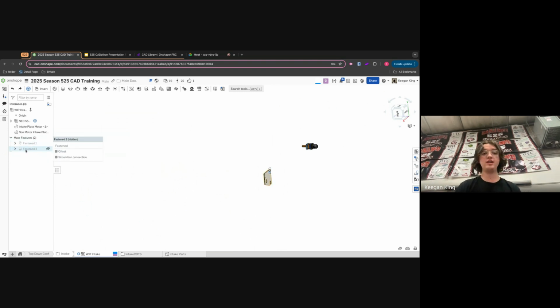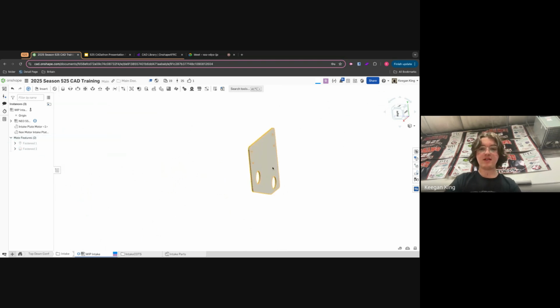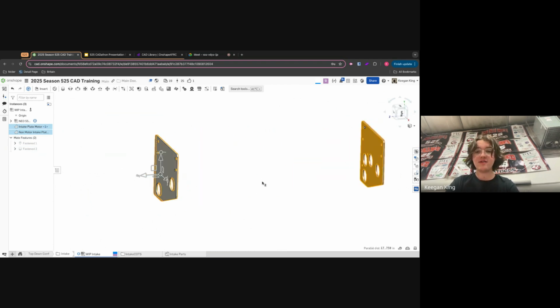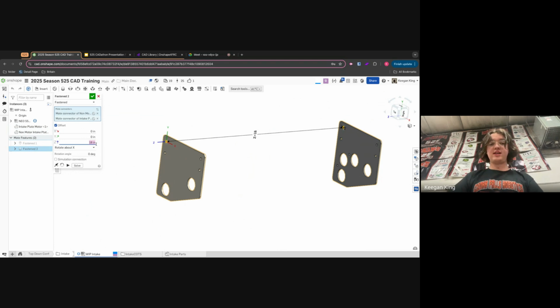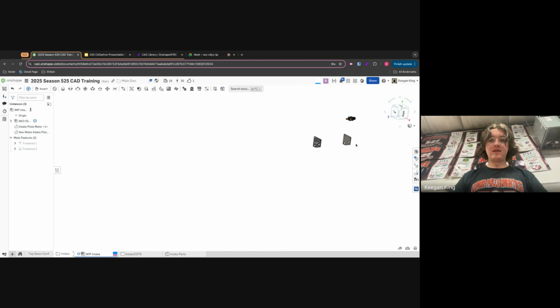And it undid some of my work. I don't know if any of you are running into that, but... Then we can confirm that there's 18 inches between these parallel points by selecting these two inside faces, and it looks like there isn't. And this is why I hit negative 18. Because when I did 18, it had them go into each other. So we lost 1/8 from one plate and 1/8 from the other. So by switching that to negative 18, that will get it.